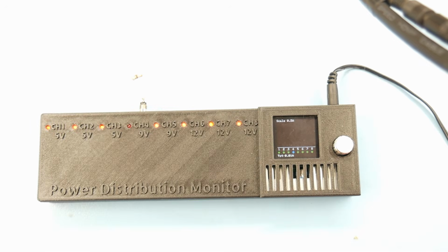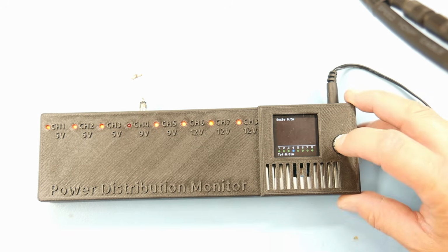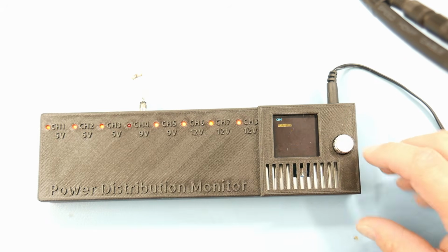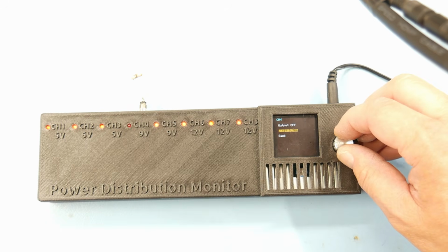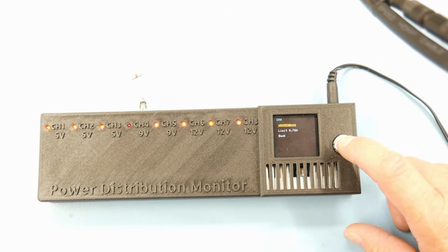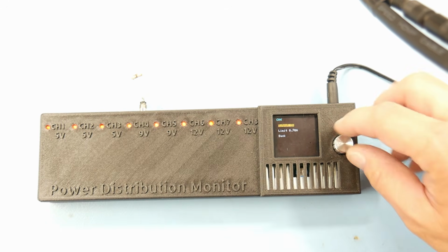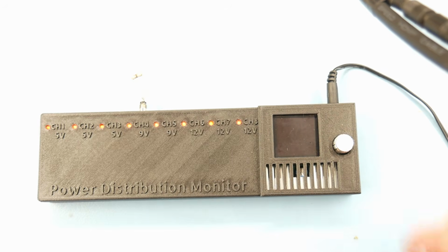Okay, when you switch it on, the first thing you notice is the display. It has some nice dots, and it says green, and channel 4 blue, which means channel 4 was turned off manually. If it's triggered, it will be red or orange. And by triggered, I mean when it has an overcurrent, because for each channel you can set the current. And right now, channel 4 is set to a limit of 0.7. Let me switch on the channel again. Now it's on. And we go back.